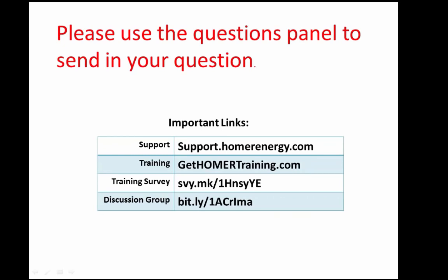Go ahead, John. We basically included those default loads so that you had a place to get started. If you need one that's specifically tailored to your situation, we also offer a synthesization module that allows you to put in minimal data to generate a realistic load profile for a location. And in addition, we allow you to import hour by hour, minute by minute data, so that if you have measured data, you can pull that in.